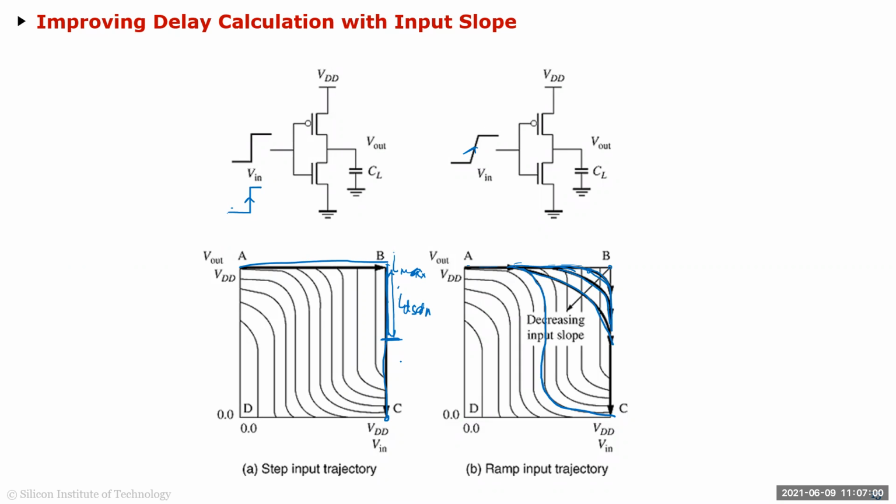So that way, when in digital they're doing synthesis, they can actually go through this .lib file and then do a synthesis and find out, oh, this path is actually too bad. Maybe I shouldn't synthesize it this way. They'll go back. The algorithm basically will retract and try to synthesize it in a different way to make the delay faster. But that's how they calculate the delays.